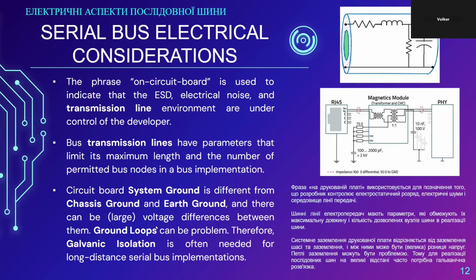When I'm talking about a piece of wire or even a trace on a circuit board, it is not just an ideal connection. Even a trace on a circuit board has a capacitance to ground. It might have a capacitance to other traces that are close by. It has an inductance. It has an isolation resistance. It has a resistance, of course, by itself, like an ohm, a resistance that dissipates power.